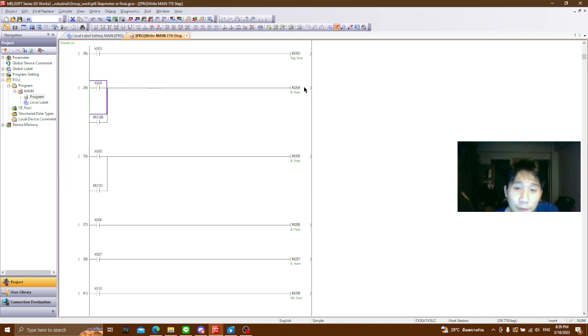Okay, and then X4 is the start button, and also this one you might be confused about, what is this? This is used for the monitor. The monitor has to send the data directly to the PLC to activate one of the specific functions that we have configured in the studio of the monitor. So we define it as M3100, same as the button start and button stop.